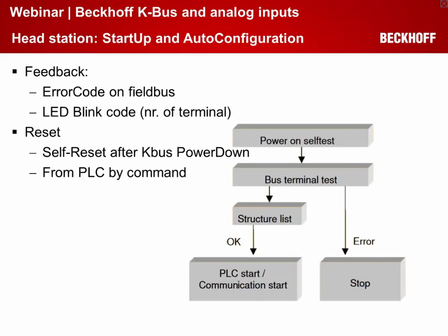When you power on such a bus coupler or a bus controller, there is a lot of self-test inside and a terminal test, and you will get the result by error code over the field bus, or you see the LED blinking code on top of the coupler outside.